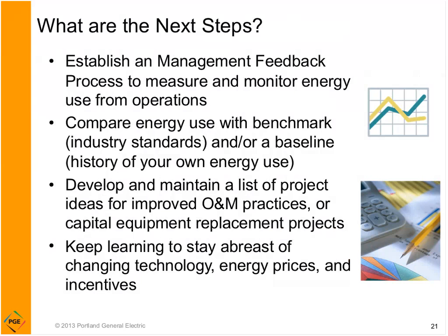So what do I think the next steps are with the tools? Look at some kind of management feedback process, not just measure and monitor, but how are you going to communicate that to people, whether it's the people using it or the management that makes decisions or the purchasing department. Compare the energy with the benchmark. There are industry standards. We've got lots of people here who can tell you the average energy per square foot for a restaurant or light manufacturing or a particular industry. I think the food processing industry says what is an average energy per pound of food processed. So there are industry standards.